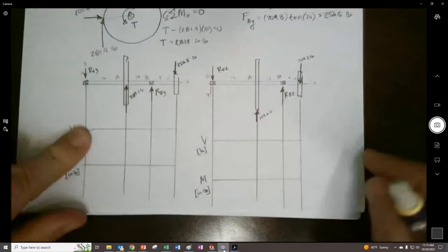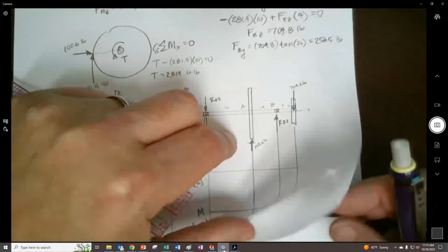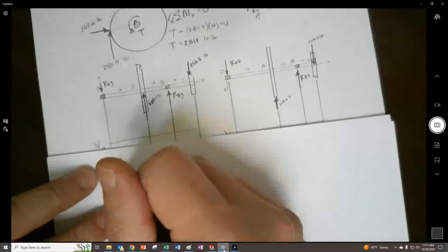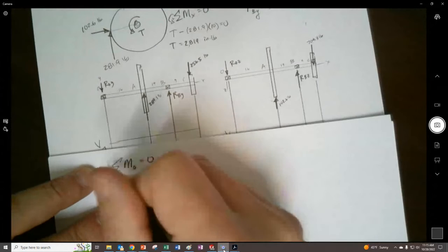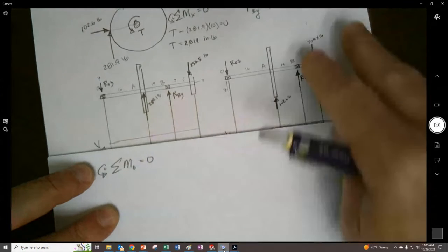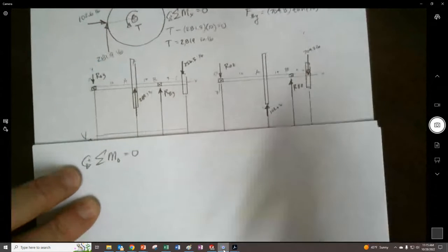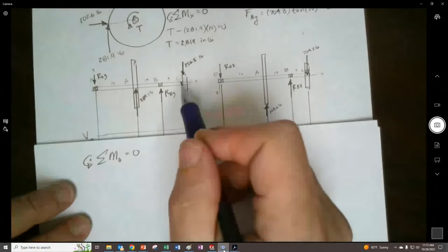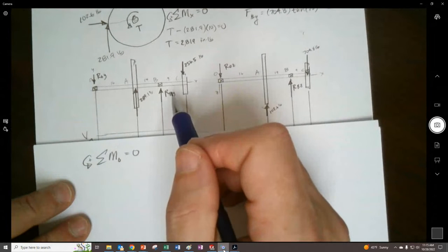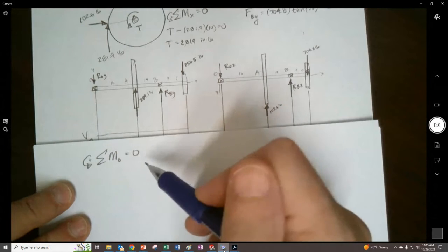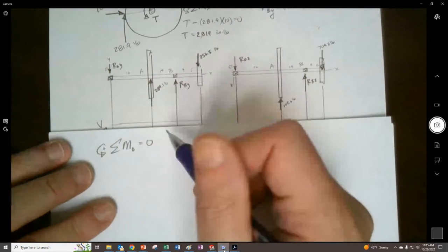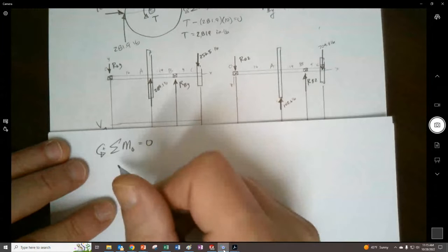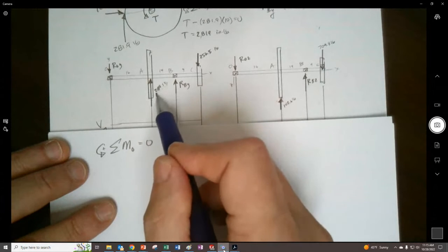All right, so I'm going to do statics. So I move the page right there and take the sum of the moments about O equals 0. And this is very, very important to me, that you're able to find these reactions and get them reliably, right? So if you can't do this yet, make sure that you follow along with what we're doing here and do practice problems where you try this out for yourself, until you're really a master of it.